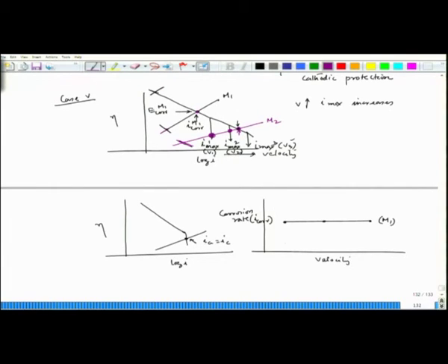So, now in V1 the corrosion rate is the lowest. Now, at V2 the corrosion rate has increased, and then V3 still increased, and then if we increase the velocity it will be constant. So, now the corrosion rate plot is like this.